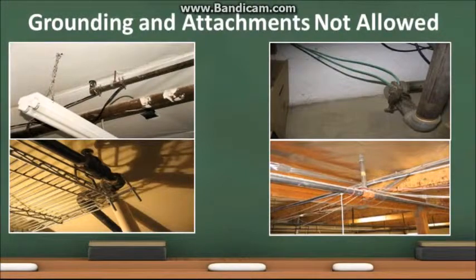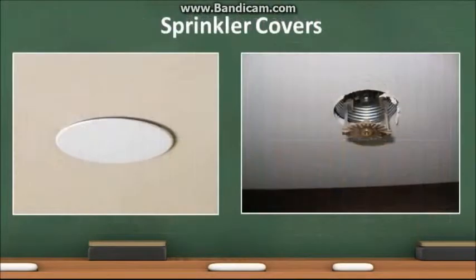Sprinkler system piping and hangers are usually centrally located to allow the sprinklers to be in prime locations. There is a tendency to attach items to these components. At no time shall any sprinkler system component be used to support non-system items. Grounding of electrical systems is not allowed.